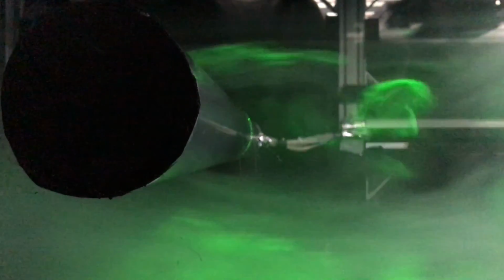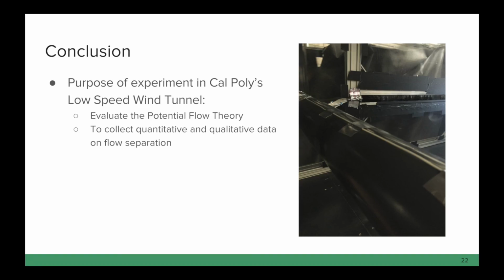The cylinder experiment gave insight into the effects of fluid forces as it moves around an object. To analyze the effects, data regarding pressure was recorded at various locations surrounding the circumference of the cylinder being tested. It is known that the flow moving over the cylinder follows the surface of the cylinder, but at some point the flow separates from its surface.